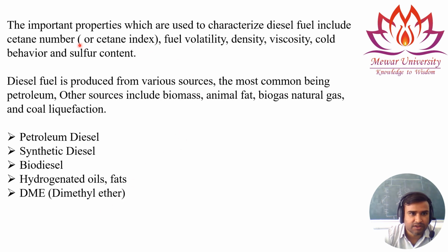The important properties used to characterize diesel fuel are cetane number or cetane index, fuel volatility, density and viscosity, cold behavior and sulfur content. So these are the important characteristic properties. Based on these, diesel is characterized as good diesel or bad diesel.